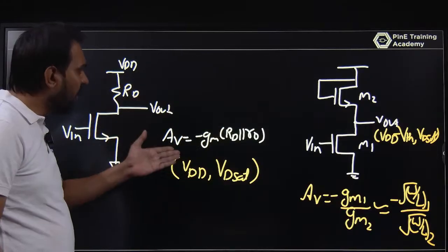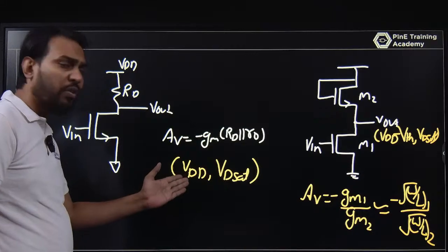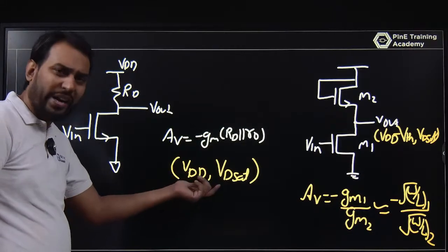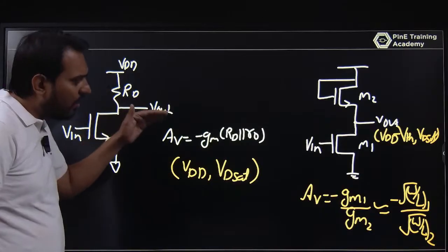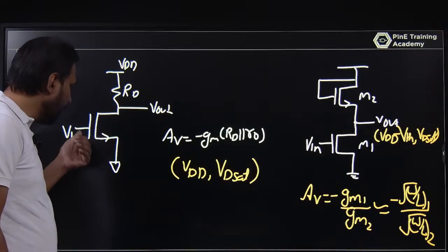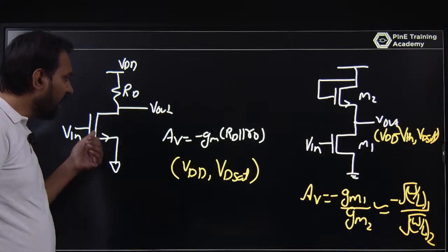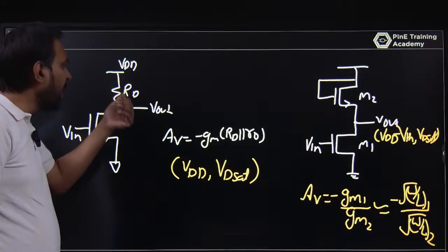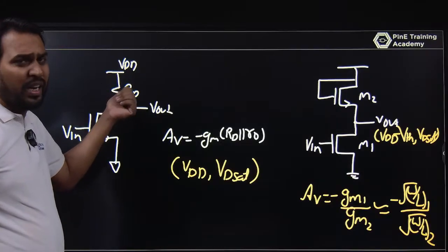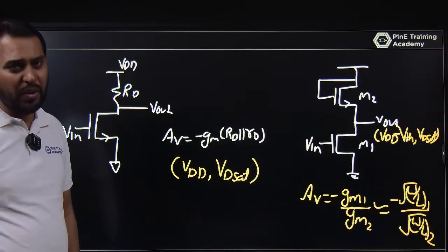This is VDD to VDS side, and it is not VDD, it is nearly about VDD. That is 1, so it will be 0.9, because as per the current going on, that has an effect. Because once the input reaches VTH, then the MOSFET is on. It is nearly VDD minus ID RD, and the current at the VTH is nearly a microampere. Okay.